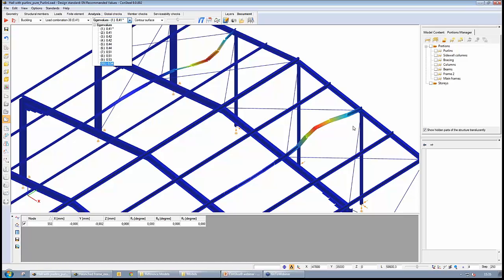In order to evaluate the realistic stiffness on our members, having in mind that these are taken to the top flange eccentrically to the members, having in mind that they have some kind of stiffness, axial stiffness and lateral stiffness as well, which can have an effect on the buckling of our main frames. But we are interested in the buckling of our main frames.